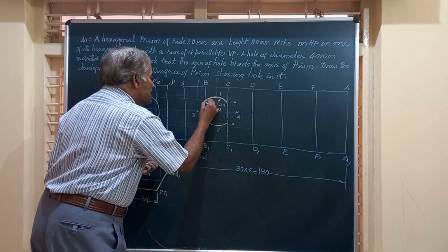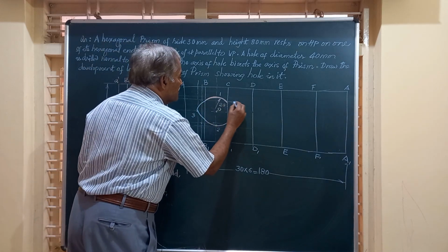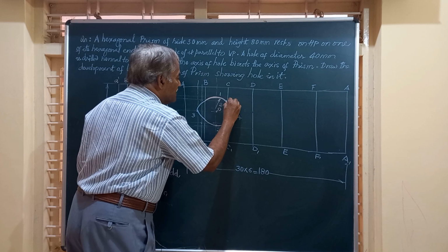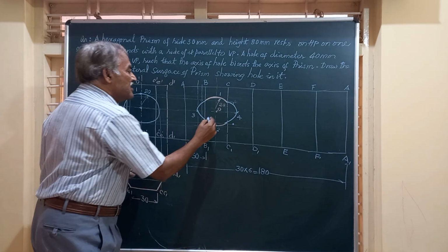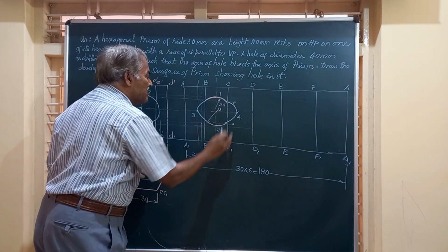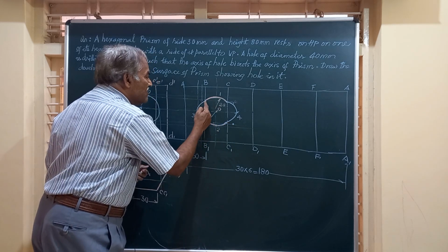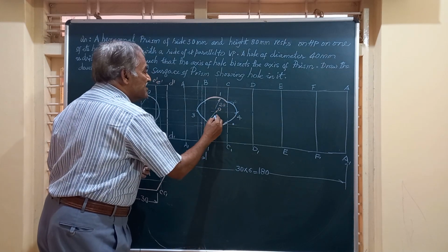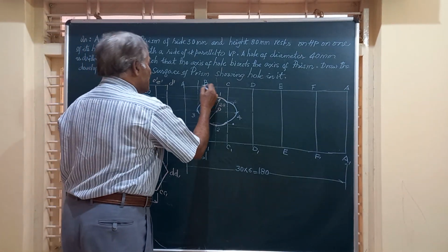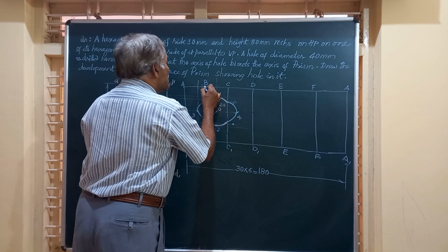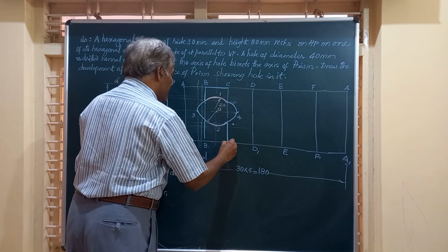So this part I am going to join by a smooth continuous curve. Similarly here, we are going to join by a smooth continuous curve like this. So friends, you will be having a portion on the rectangular face as exact arcs, and the points outside this will be a smooth curve like this. Friends, this is how the hole drilled on this surface, that is B1C1, looks. This is how you get it on that surface.